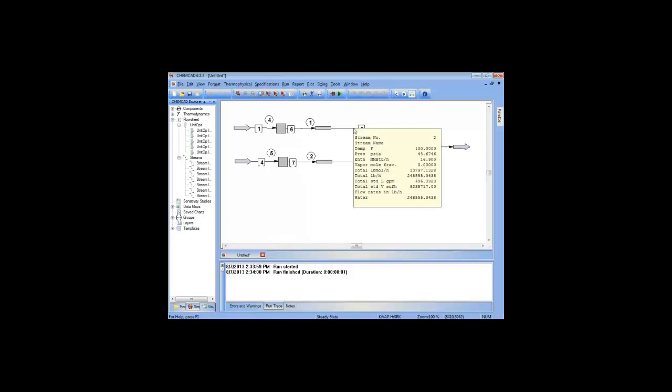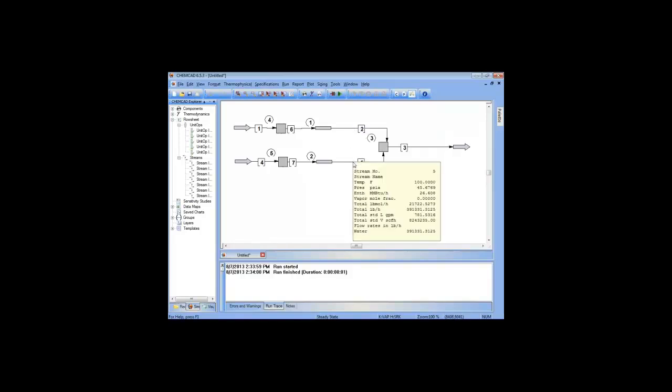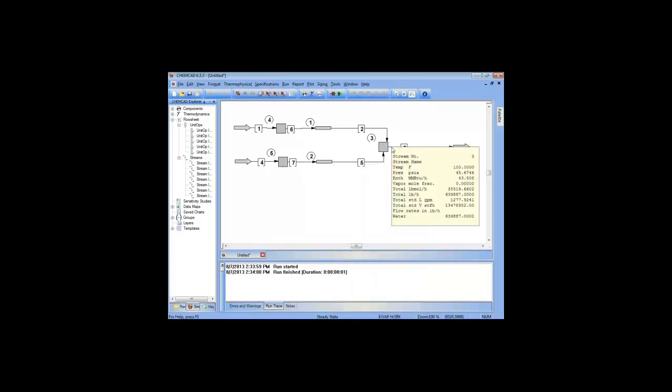So that is what is actually needed in order to balance this flow and have both branches come out at 45.6, to have the flow rate and the pressures balance through both branches. And therefore the pressure at stream 3 coming out is balanced for the whole system.